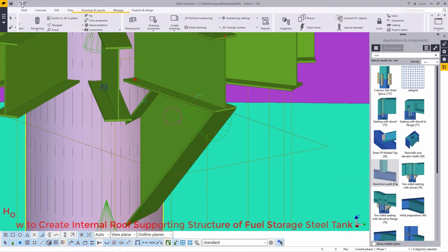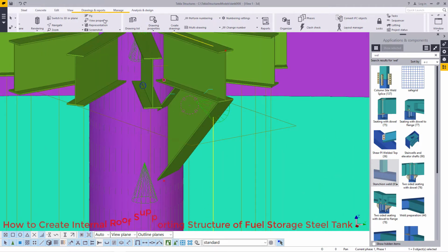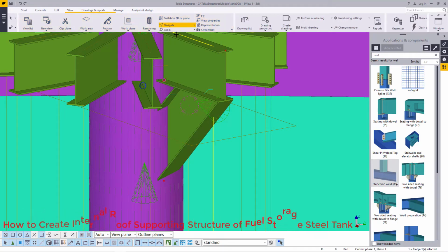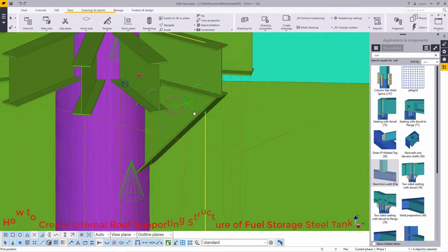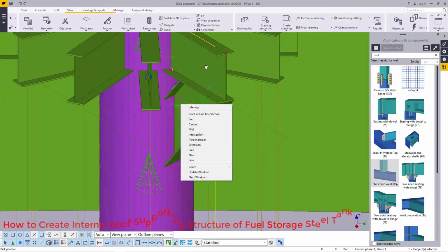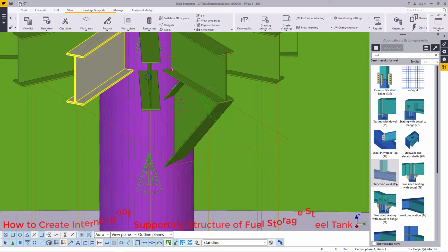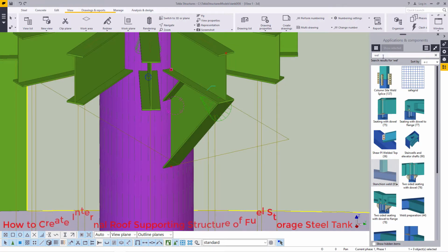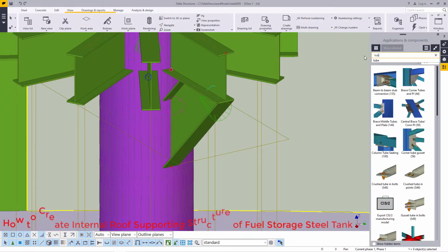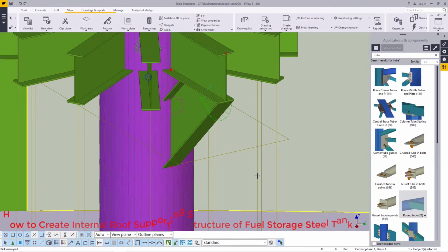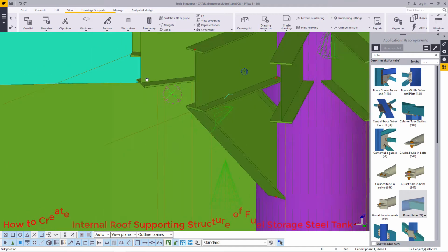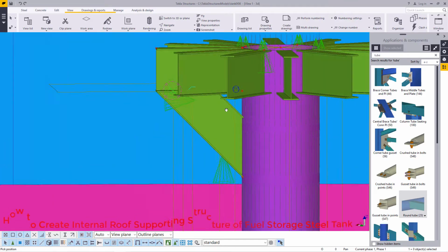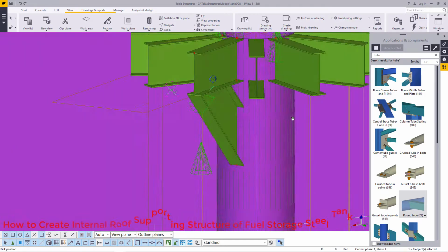So what do we do? Just undo and use the best tool to create that weld, the same we used on this top end. Now let me just undo that and come to tube here, just type tube and snap on that, and I want to weld this to that. So I think the weld has been created, and this is how it looks, and it's well connected to the pipe.